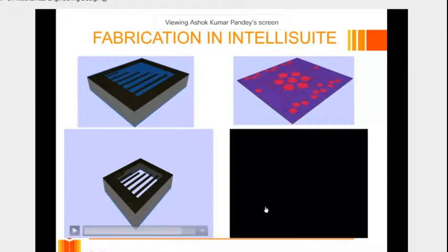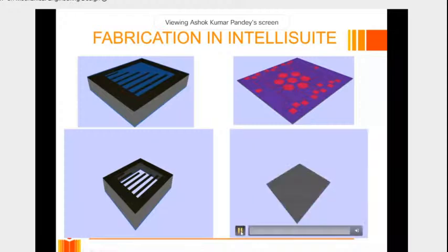Okay, similar to this, the same thing: deposition, then patterning, etching, then metal deposition, then etching away all the part will give you these multi-stage ones. That's why you have first etching, then you do it again.